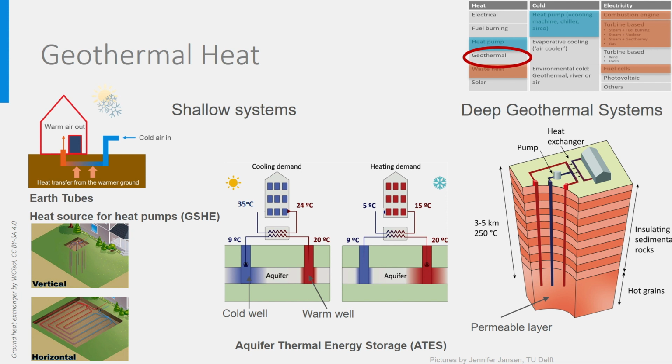In terms of primary energy and CO2 emissions, earth tubes, ATES and deep geothermal systems require pumping power. The electricity needed for the pumps may be significant, especially in the deep geothermal systems. However, this electricity represents only a small fraction of the resources and CO2 emissions that are produced when using combustion boilers or electrical resistance heating. In most national codes, geothermal heat is just considered to use zero primary energy and to have zero CO2 emissions.